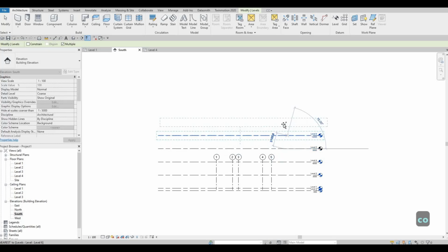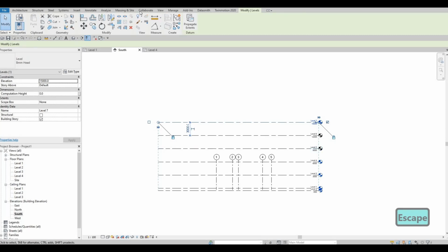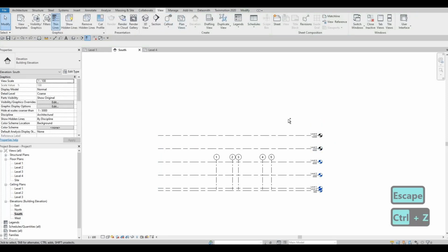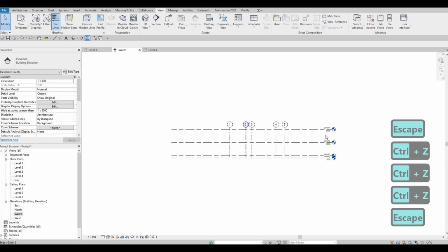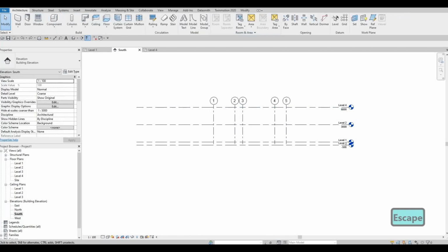As you can see, it's so fast to add. But as you can see, there's nothing added here on our floor plan, so you just need to do the View and then Plan View. But if you're adding just a couple of floor plans, better do the level instead, so that you instantly add all of this right there.